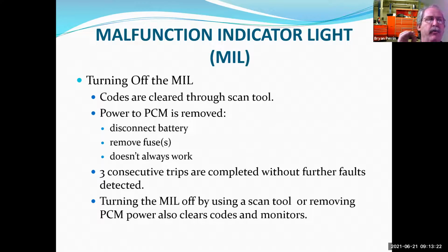So unfortunately, what happens is people will go to XYZ Auto Parts with a check engine light on. XYZ Auto Parts gives them a code number and then clears the memory. And then the customer brings the car into the shop and says, I want this code number diagnosed. The customer's gotten rid of all the diagnostic data that we would use to diagnose the code in many cases. So now I've got to tell the customer, we're actually going to charge you more because I have to go drive the car and get it to fail again so I can diagnose it, because you got rid of all the data.